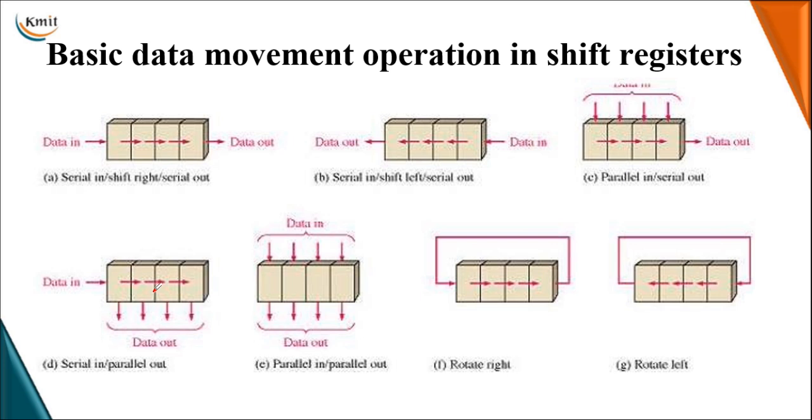Till then, it will be an invalid state. If it is loaded fully, then only the outputs are treated as valid outputs. Next, parallel in, parallel out. This is the method of entering the data in parallel form, as well as collecting your data from the register in parallel form on a single clock pulse.